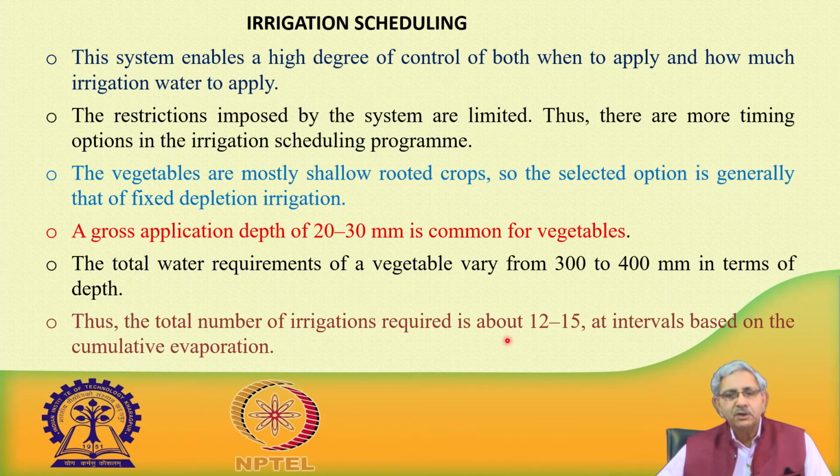So, here in a micro irrigation system, whether it is a micro sprinkler or a drip irrigation system, we are mainly focusing that soil moisture depletion should not be more, and it should be at field capacity, so that the plant does not have to suffer due to moisture content unless and until there is a shortage of water supply. Then a deficit water supply program can be made, where a strategy can be made to supply water in a deficit way without compromising the yield of the crop.